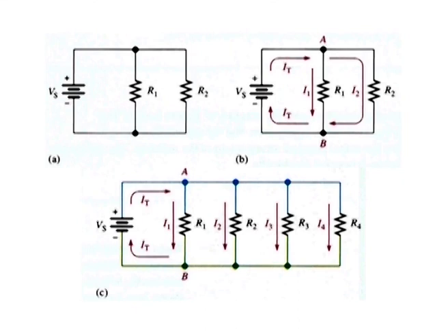Two resistors connected in parallel are shown in figure A. As shown in part B, the current out of the source divides when it gets to point A. I1 goes through R1 and I2 goes through R2. If additional resistors are connected in parallel with the first two, more current paths are provided between point A and point B, as shown in part C of the figure.